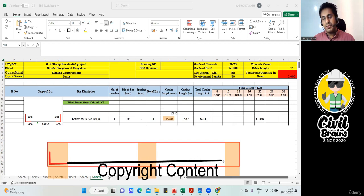It will come completely up to here. And then this is a red portion, which will come like this, and then it will get something like this. But practically on the site, this is not possible because this entire cutting length, we have got 13.570, which is greater than 12 meter. So in that case, what I'm supposed to do, I'll bring my bar somewhere here.